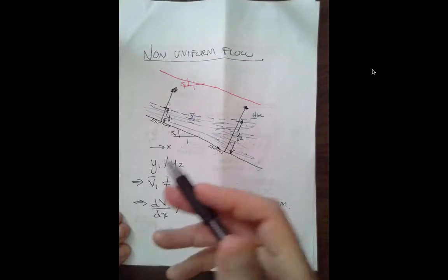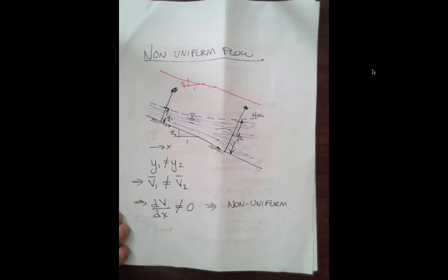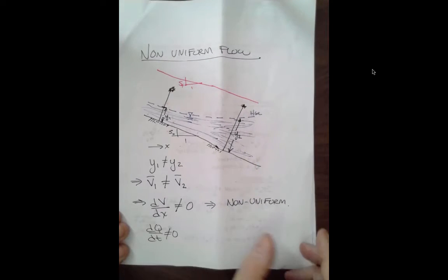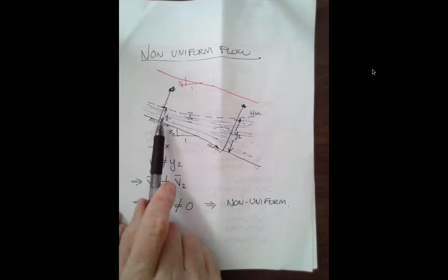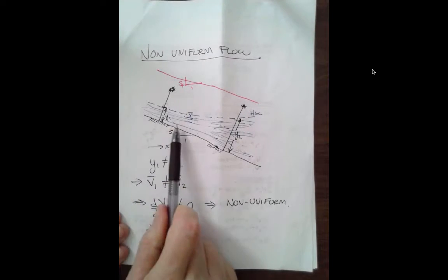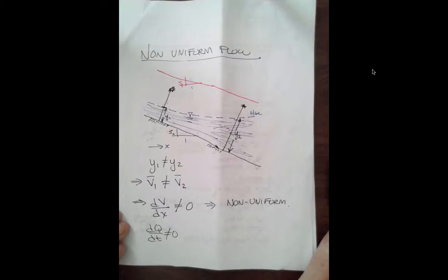If this happened to also coincide with steady flow, in other words, dq/dt was not 0, for this to happen, the only thing we would experience is a convective acceleration term. Apparent acceleration that is a consequence of spatial variation in velocity, but not temporal variation. Temporal variation, as you recall, was called the local acceleration.